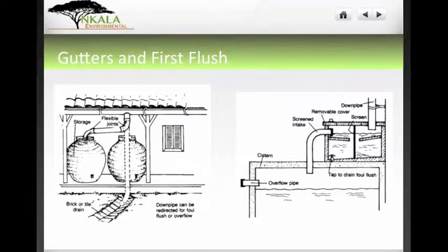If your gutters are too flat, especially if you're using bamboo or wood, which is not as regular a shape as metal, you want to make sure you have a good slope so that you're not pooling water, or catching sediment and nutrients or leaves or things like that that build up and can attract animals, insects, and so forth. You want to make sure there's a good slope so that all those things can be prevented. Mosquito breeding is prevented.